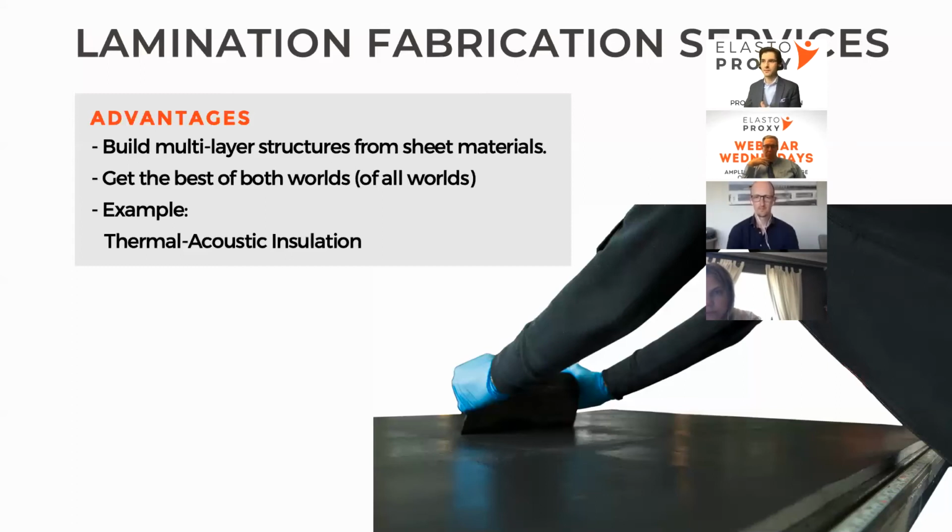So we had to have on the top layer something that will keep the heat in, so we had to use a silicone facing. We had to consider a polyester foam for the high frequency sound. We had to use a PVC loaded barrier for the low frequency sound. And then we used another silicone foam, again, to keep the heat within the compartment. That does not exist in the market, so we had to come up with it from scratch, but we were able to laminate these together and at the same time cut the pieces out, depending on where it was going in that compartment.